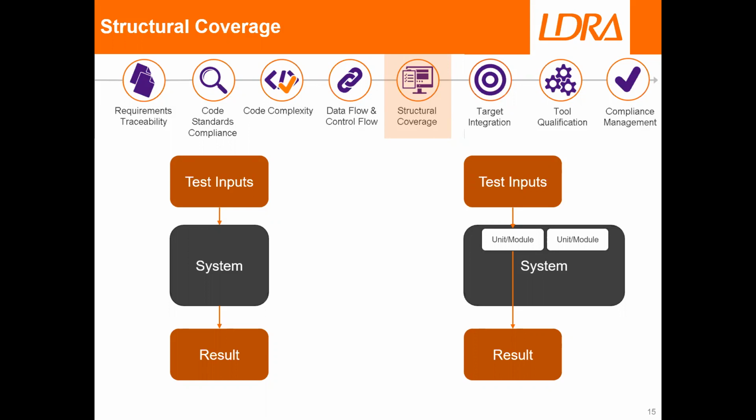And generally speaking, the most cost-effective approach is to reduce the verification burden and obtain coverage at the highest level of functional testing possible. And some projects use coverage as a way of checking test effectiveness across the software within an environment that is different from the actual shipped device. So for example, executing on an Intel or AMD processor instead of running on embedded.